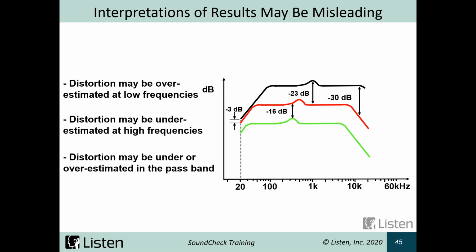So instead of traditionally measuring the THD like this, by measuring the THD at the measured frequencies, it's going to remove the effect of the DUT frequency response, as well as the frequency response of the test space and any irregularities there. And it's going to actually plot the harmonics where they occur and give us a more accurate representation of where the distortion is being caused.